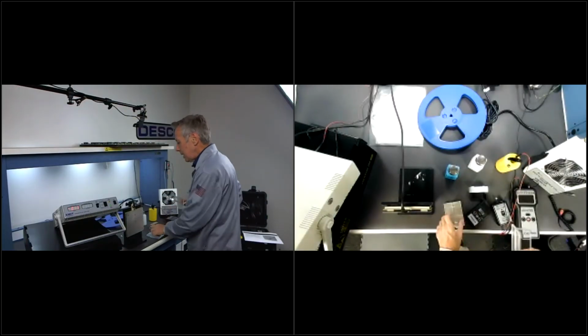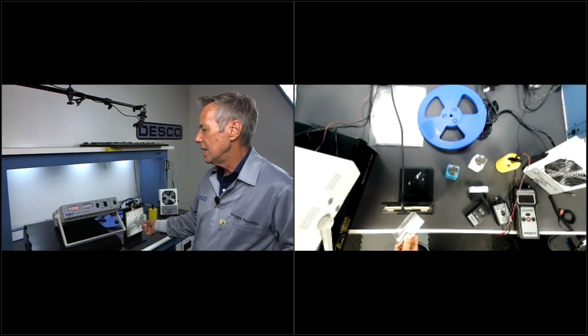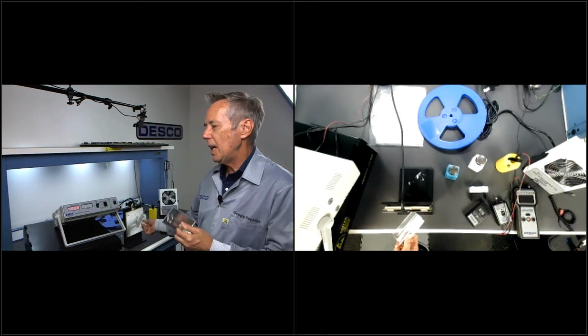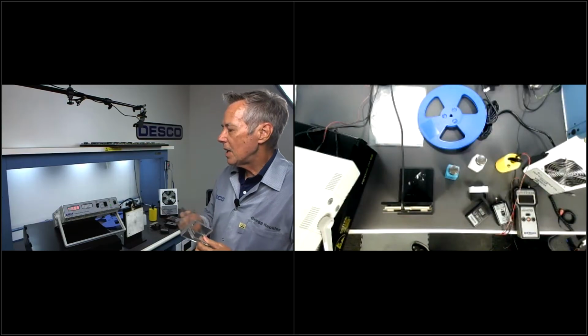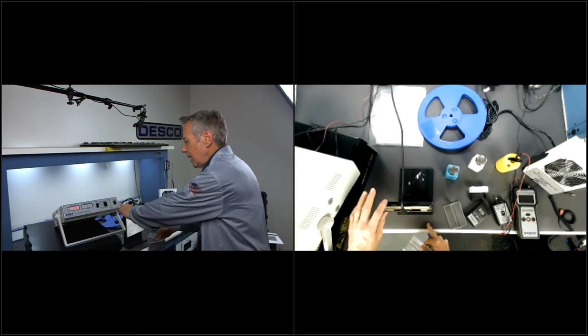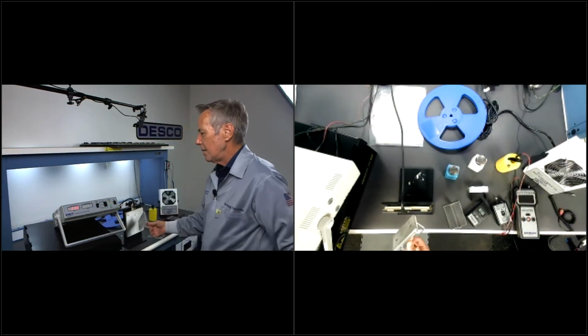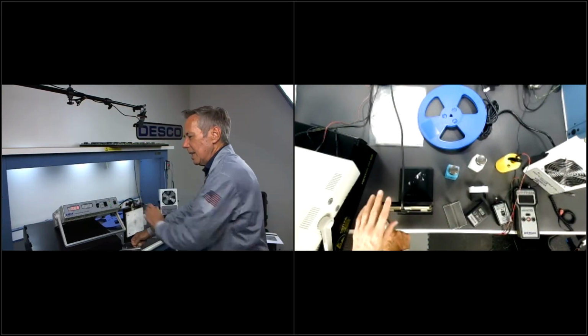Now I'm going to give you another example. I have my charge plate analyzer here, and if I hold this field meter up there right now, the charge plate analyzer is reading a little over 1,000 volts, something like that. Again, I'm going to charge this up, and let me ground this away here, zero it. So I'm going to touch this. Now I have 800, almost 900 volts here. Again, the difference is, I'm going to ground this away.